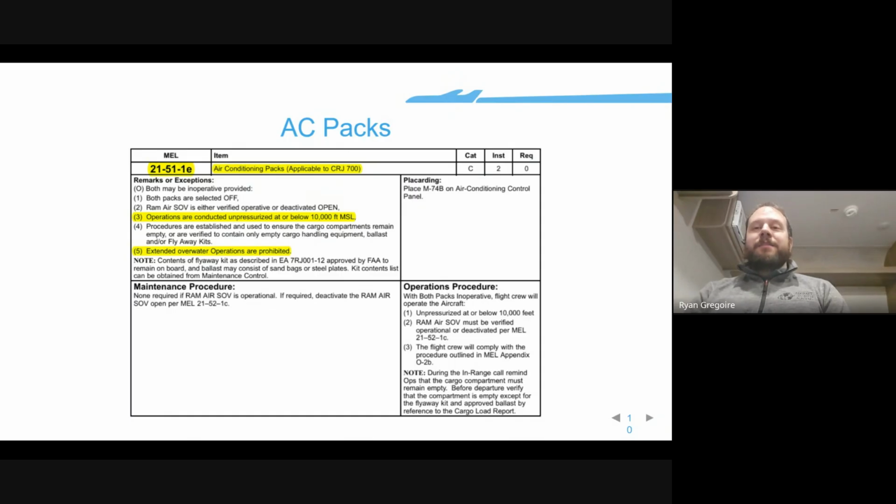And at 10,000 feet, that is going to have an extremely prohibitive fuel burn. We fly at high altitudes because at high altitudes, the jet engines are more efficient. At lower altitudes, the jet engines burn a lot more fuel. And when you guys actually get into flight planning, you'll start seeing those significant increases in fuel burn at lower altitudes. So the fuel required to operate a passenger carrying flight at or below 10,000 feet would be extremely prohibitive.